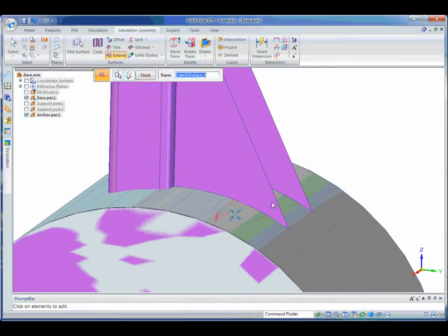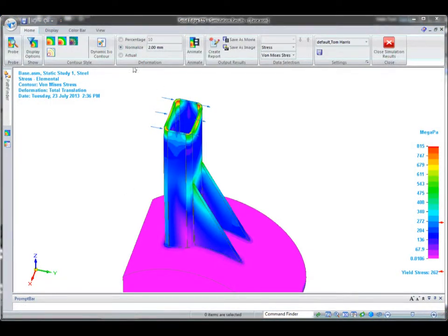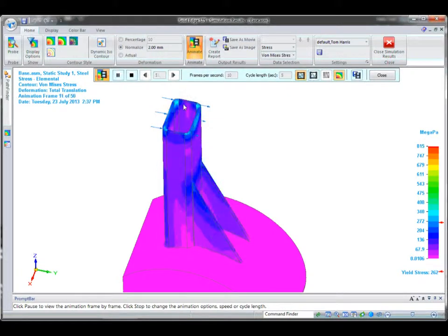If you wish to join a solid to a surface, just be sure to extend the surface slightly into the solid instead of just touching it onto the solid. This avoids the problem where a planar surface will tip over on applied force due to solid element nodes not supporting rotation when connected to surface element nodes.